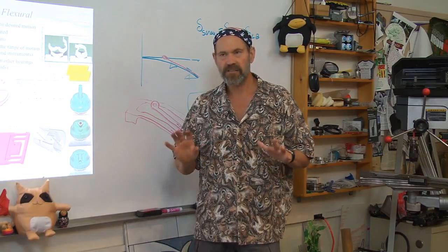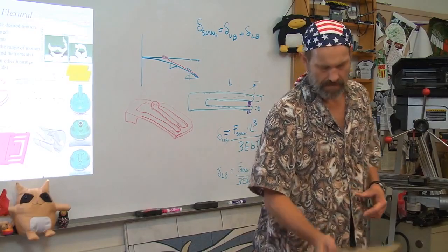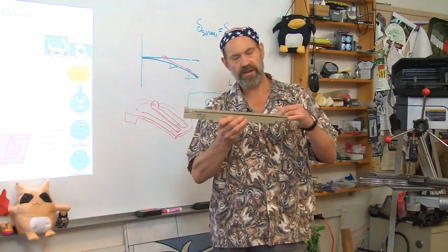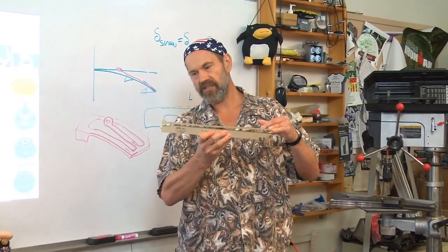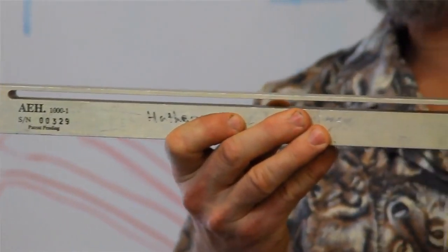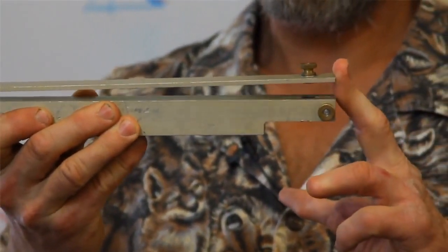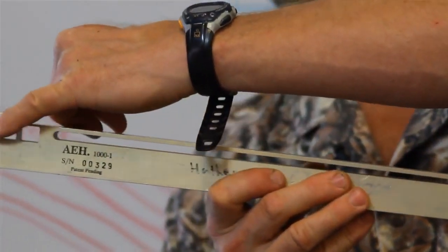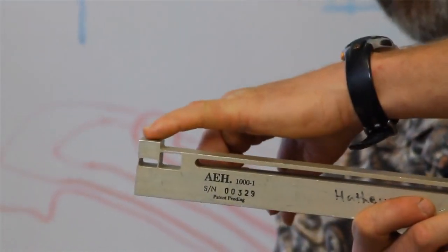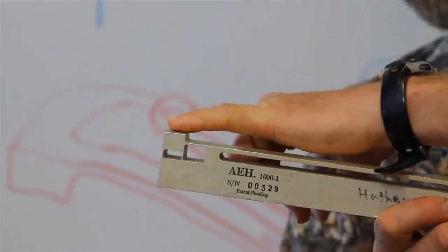There's a fantastic array of flexural elements. Here's another flexural bearing which is used in a transmission ratio. My friend Nelson Hathaway invented this design. When I move this structure up and down, there'd be a micrometer here where I could control this motion to the thousandth of an inch level, it's creating a strain field over here that is causing this surface on this little 4-bar flexural linkage to move that way.